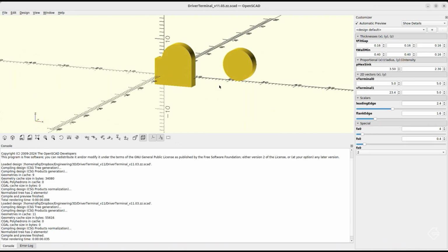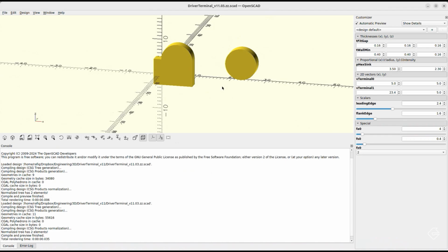Remember, every 2-dimensional object in SCAD is created flat on the XY plane. So when I'm describing the X and Y locations, I literally am describing the X and Y locations on that plane. But because we've rotated this whole thing 90 degrees along the X-axis, that Y direction becomes the Z direction. So I mentioned this in the last episode, this confusion of axes before rotation and after rotation is critically important, and you have to keep them in your mind when working on these 3-dimensional models. And when we render that, sure enough, we see the rectangle that we're pretty certain we were creating.